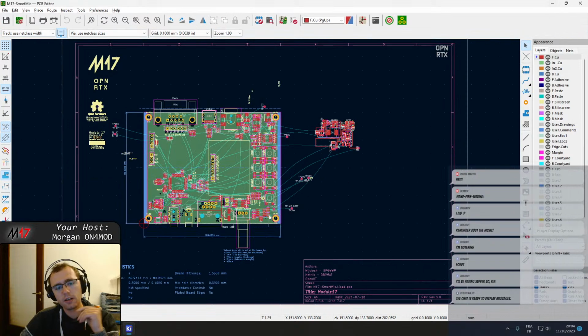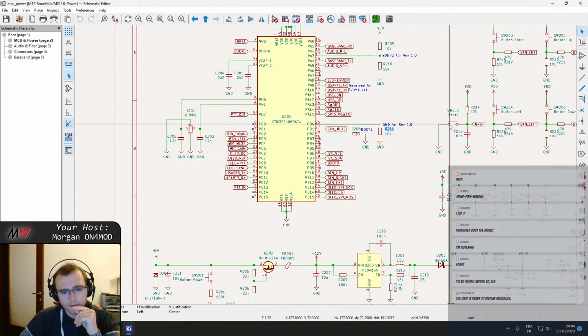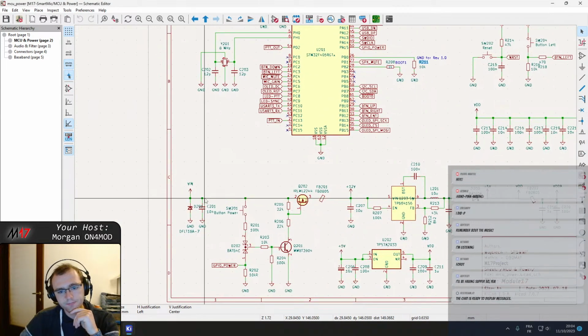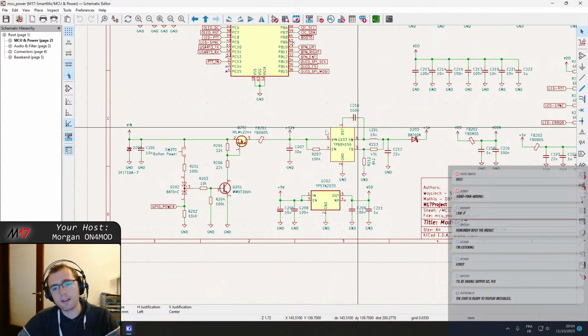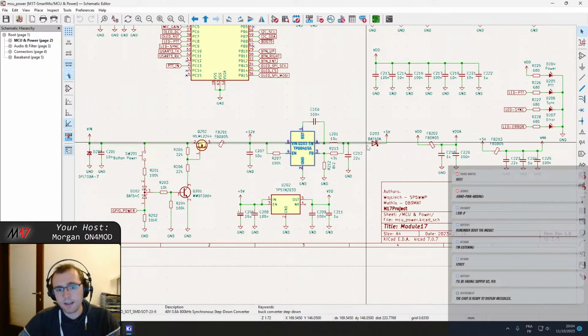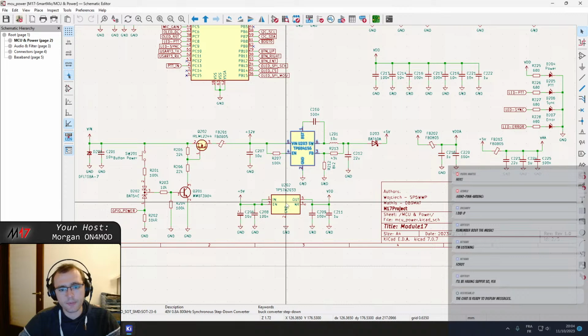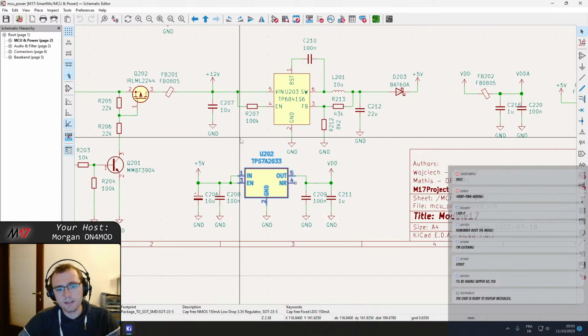So I think maybe the first thing we should try to do now, we might have a small issue with the power supply actually. Currently you have the 12-volt input, which is stepped down to 5 volt, and then this 5 volt is stepped down using a DC-DC converter which works at 800 kilohertz, and then it's stepped down to 3 volts or 3.3, I think, using an LDO.